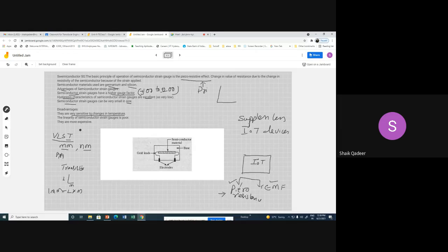That's why it is not advisable to rely on the semiconducting implementation of a strain gauge without shielding or protection against temperature. Always remember, all implementations of semiconducting elements in electronics have problems associated with temperature.